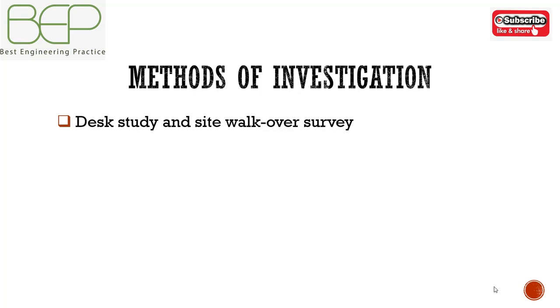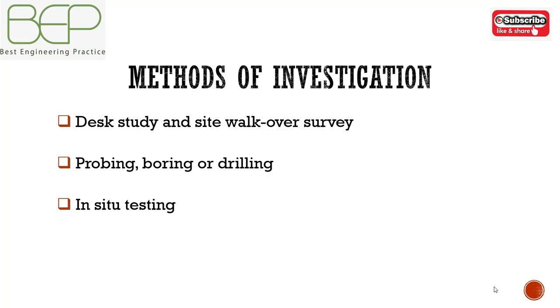Soil investigation should at least consist of a desk study and site walkover survey, gathering existing information of the site, probing, boring, or drilling to determine the soil profile and variability of the ground, in situ testing to obtain data on soil conditions, and sampling and laboratory testing for direct determination of the properties of the soil.